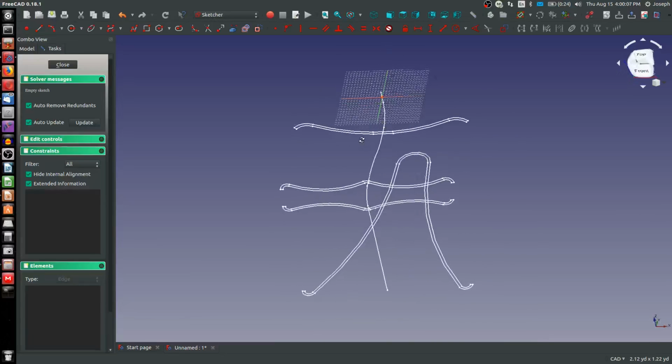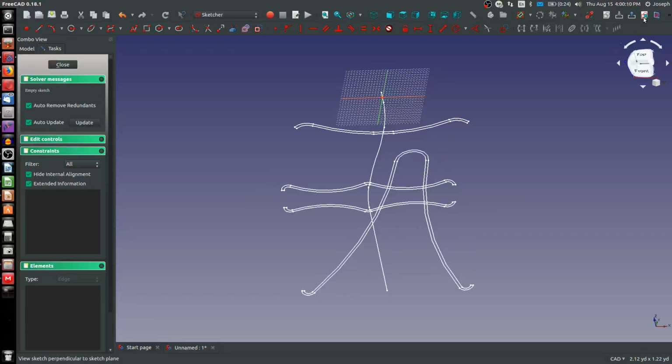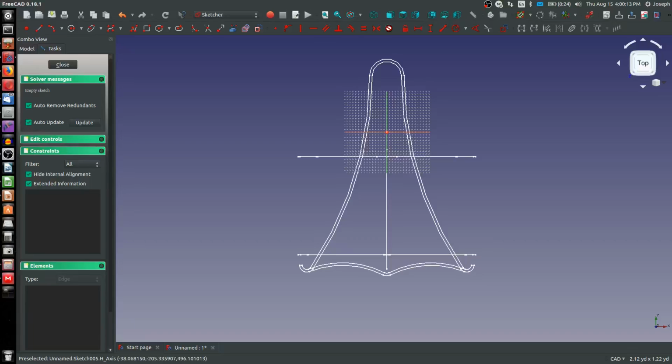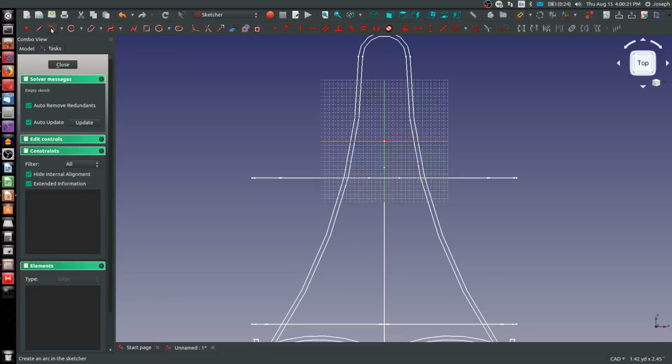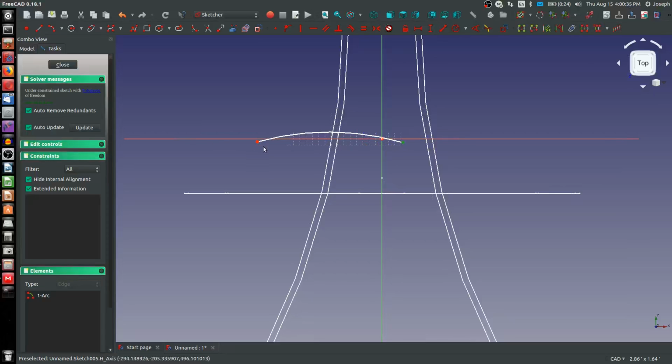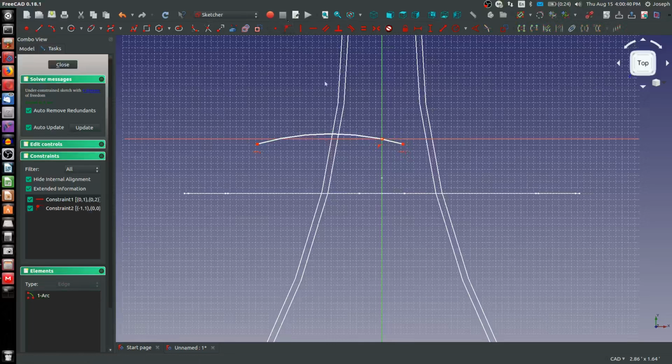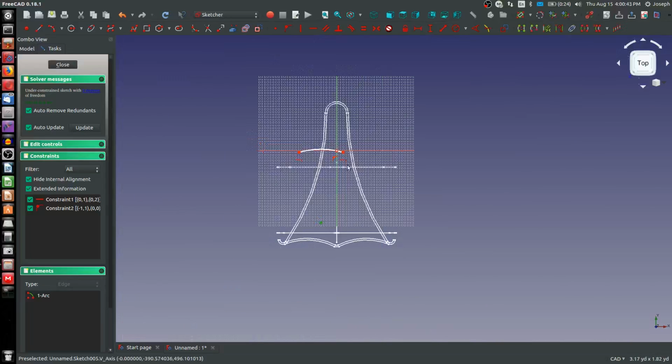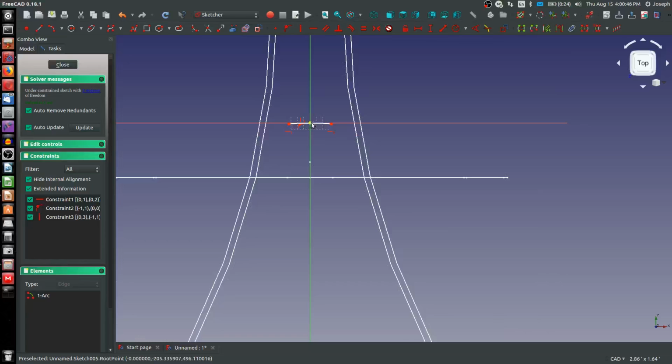So that's what we've got so far, and notice that these sketches are concerned with the front. Now what profile do we want for the back of the chair? Let's go with another arc. Of course we want a rounded back end. I've got a rim point arc, so I can simply draw it here, highlight the 2 endpoints and make them horizontal as we have, highlight the origin and make it coincident onto the arc, and then I'll make my center point of this arc vertical with the origin.